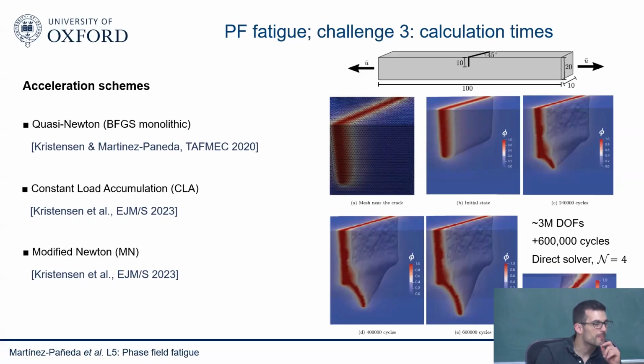What might be the possibilities of reducing the computation? So what can one do? Yeah. The cycle jumping is a good idea because when you're running millions and millions of cycles, it doesn't make any sense to resolve each one. For sure cycle number 200,000 is going to be equal to 200,001.